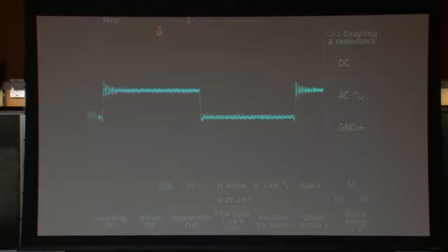Okay, that's much more pleasant in terms of the amount of switching. You can see it's still noisy, stuff's still going on, but not nearly as bad as when I was really sloppy about both the loop inductance and the node capacitance.